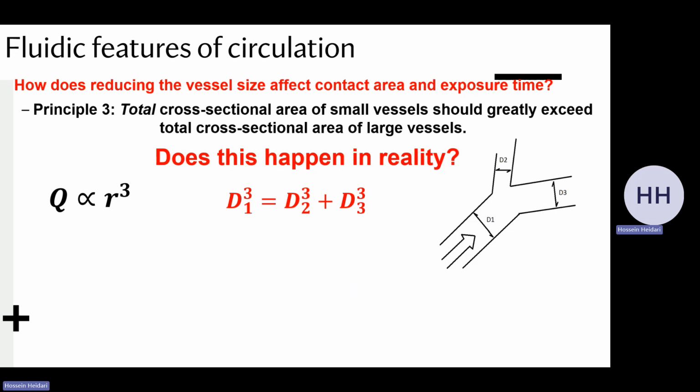And if we figure out that these two on the outlet side are actually larger in terms of the sum of their cross sections, then we figured out that we've actually slowed down the flow going from the inlet to the outlet, because the overall cross-sectional area has become larger and therefore the flow has slowed down. Is it clear for everyone what we're doing now? Okay, all good?